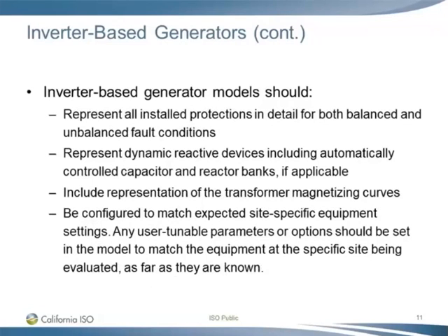Similar to synchronous generators, the inverter-based generator models should represent all installed protection in detail for both balanced and unbalanced fault conditions. All dynamic reactive devices, including automatically controlled capacitor and reactor banks, should be modeled if applicable, and the transformer magnetizing curve should be represented.